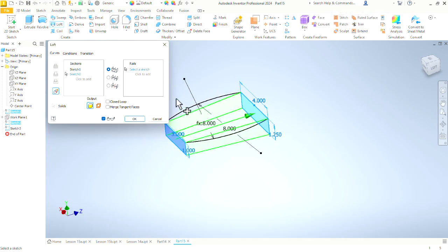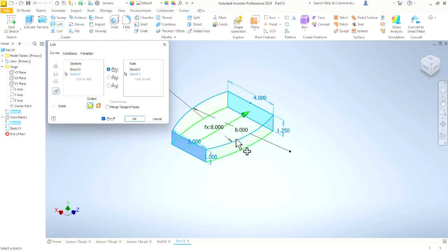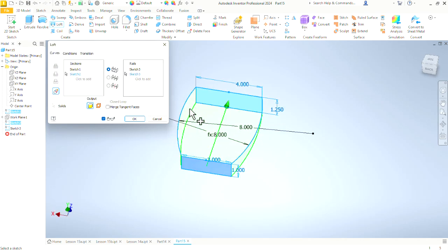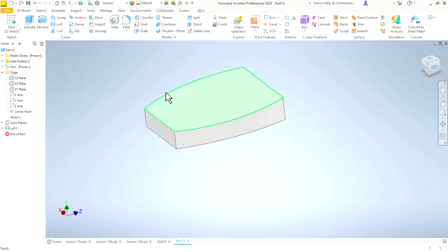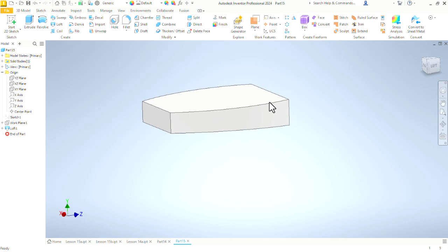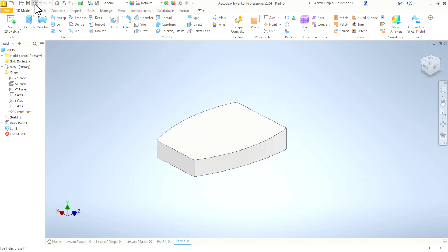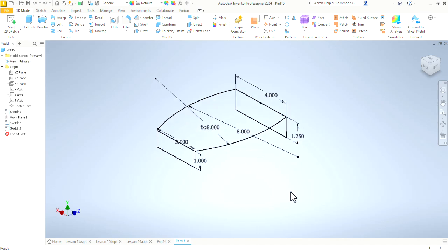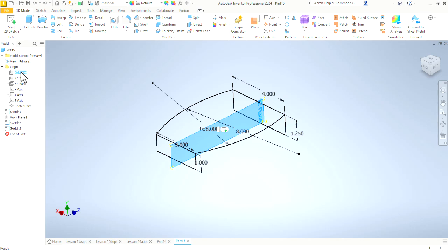Let's look here. Let's add our rails, select a sketch, it is ready. I click one side of that sketch, it shifts everything out to the left. But I click this other side, and now it stretches both sides out. So I've got both sides of this boat bulging out a little bit, but notice it still has a flat bottom because I can add even more control. Let's hit undo. So it takes that loft off of there, and we're going to sketch one more time,